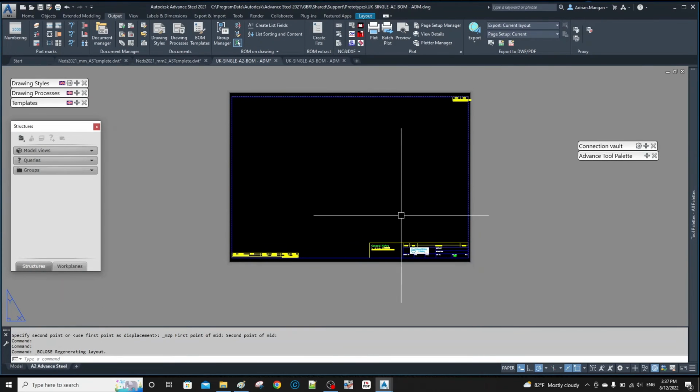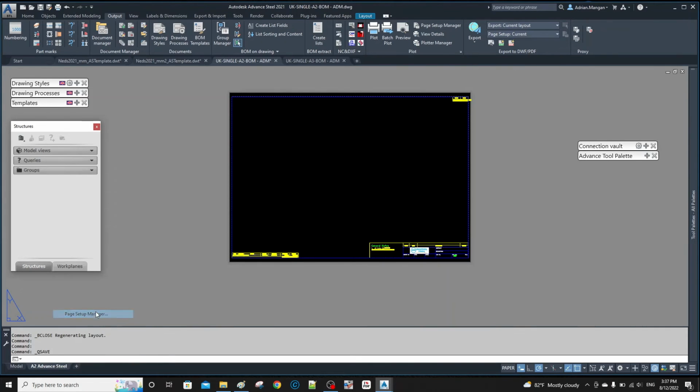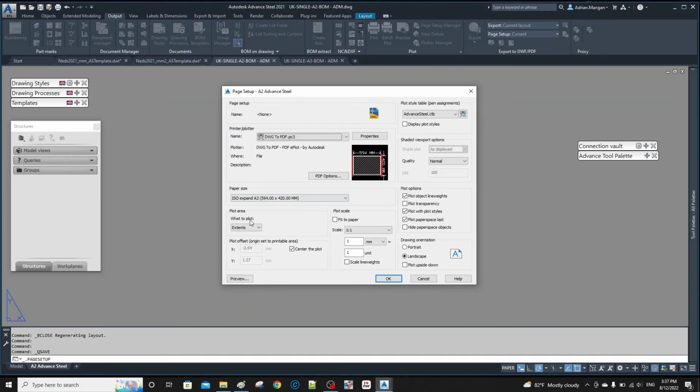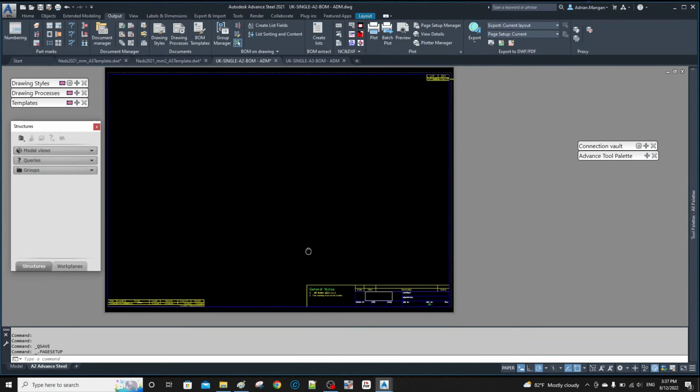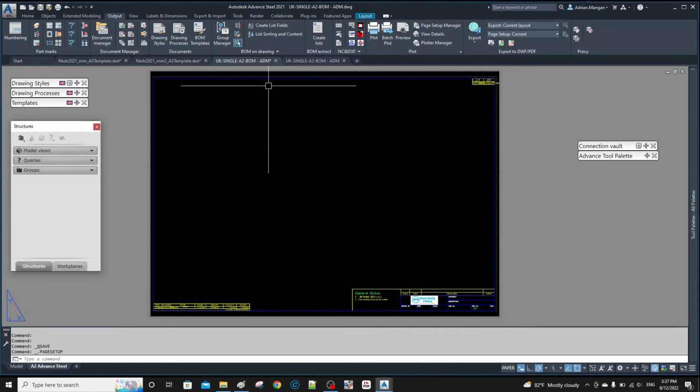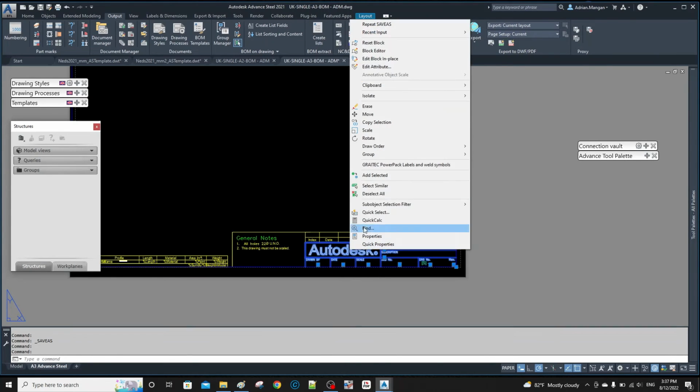Alright, so now I've changed that, so let's do a save, and then come back down here, and page setup, modify, change this also to layout, CTB and all that's okay. Landscape is good. Plot line weights, you can change these when you're plotting. That's quite helpful actually. Okay, close. Okay, and that's good. Now save that, and then go to the other one and block editor.